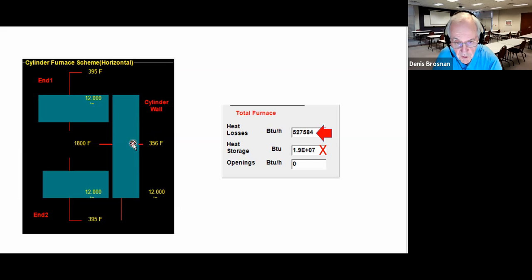You're going to have to go in and stop the process and replace the section of kiln if it gets a deformation or wrinkle in it. So this is very important for us, and of course most rotary kiln operations are going to have some kind of sensing device monitoring that doesn't allow you to exceed that temperature.